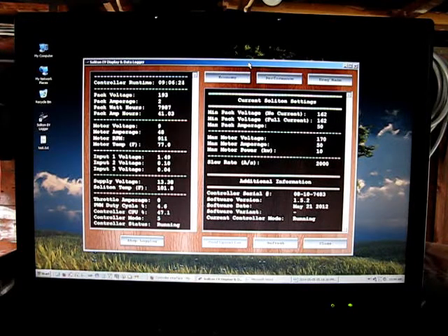Now this is weird because, as you can see, the motor RPM is actually dropping. And also, what I noticed when I came in this morning was that the motor was spinning quite a bit slower, hovering at about 300 RPM. So for some reason, it's entered into this state where it's reducing its RPM down to a very low value, and then it hunts and comes back up. But this whole process takes several minutes. It's not consistent at all. So I'm not really sure what's going on with it.